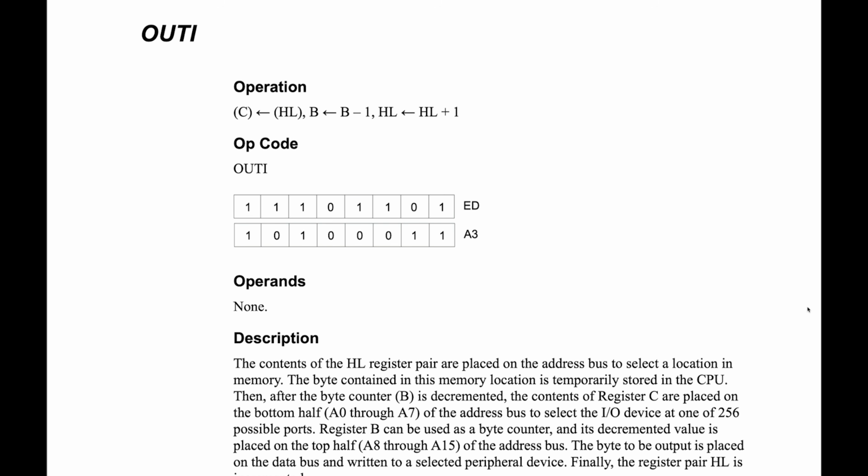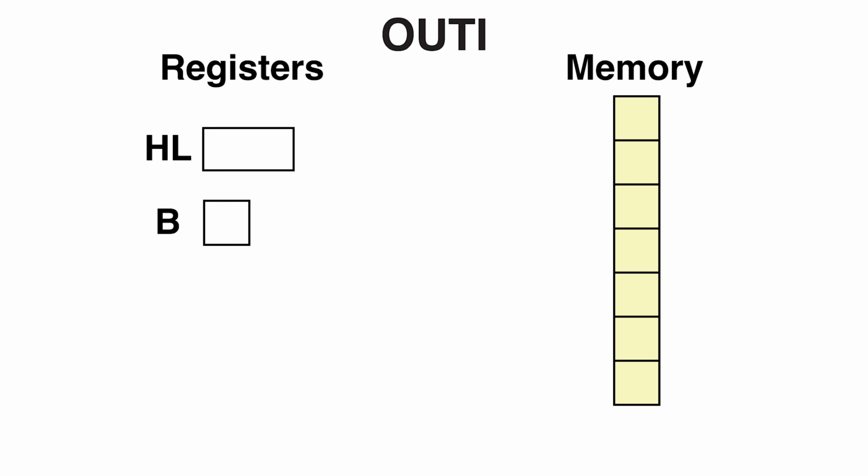If we were using the lower byte of the address bus for I/O, like a normal Z80 system, the gate array would need to have an extra pin or 2 just for that. So in this case, Amstrad managed to squeeze all of that in a 40-pin package by pulling that weird optimization. They saved some cost, and it made it so that all I/O on Amstrad worked completely differently to all other Z80 computers.